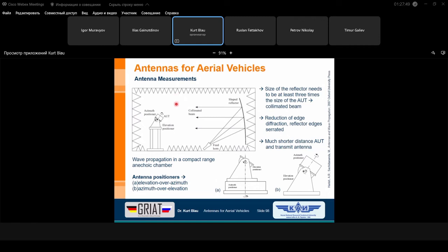If you go lower in frequency, down to, for instance, 100 megahertz, the frequency of ultra shortwave radio, then the absorbers have a length of about 1.5 meters, or minimum 1 meter. The length depends also on the amount of the reflections. The longer the pyramids, the lower the reflections. Okay, this is what I wanted to add.